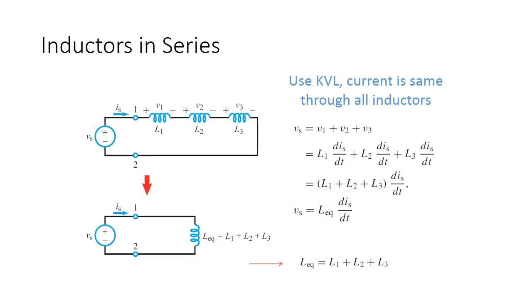Like we've just done capacitors and resistors in series and parallel, we have to do inductors in series and parallel. Inductors in series are going to add together just like resistors. That's because, and we'll look at this later, the number of coils in an inductor has an impact on its inductance, because more coils gives you more magnetic field. So if you add, let's say L1 has 5 coils, L2 has 5 coils, L3 has 5 coils, you can think of it as 5, 10, 15 coils.